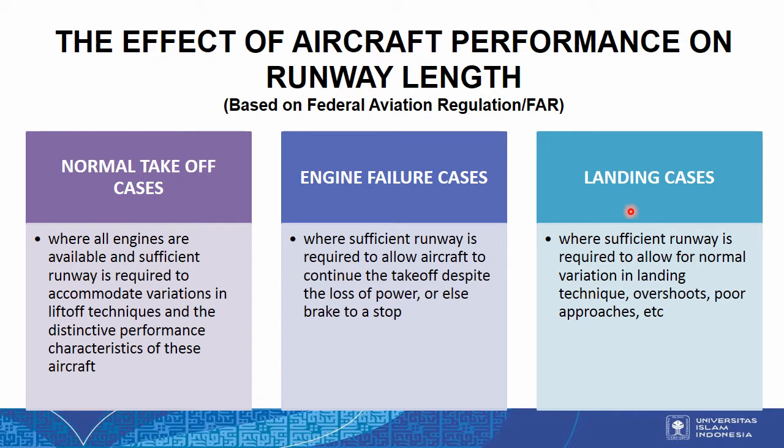And then after we know the three cases, the runway length is the longest runway needed among the three criteria. From these cases we will know the length required, and also from the landing case we will know the length of the runway that we need.